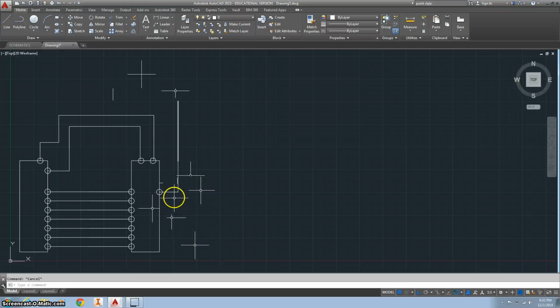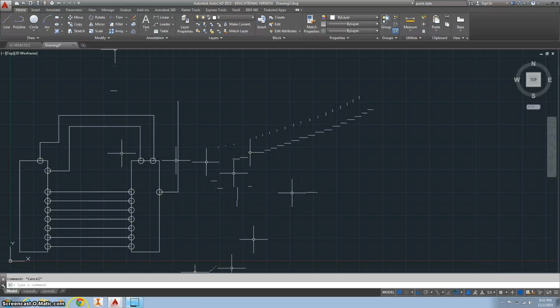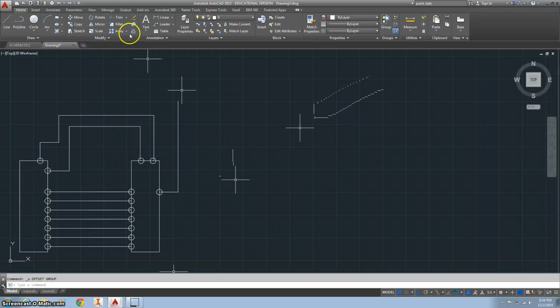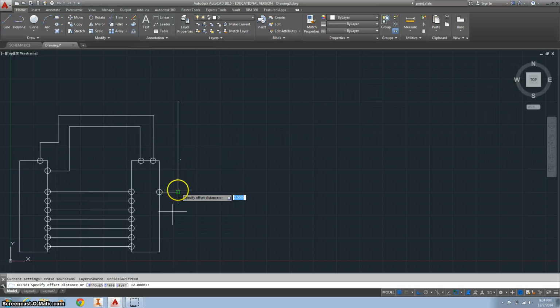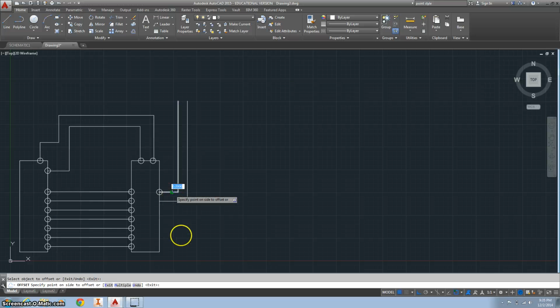and is it my graphic card, or why didn't it work? Look at all this stuff. Alright, so let's try this again. Offset, click on the line you want, specific. Alright, then it asks for a specific point. I'll just click this one. We want to select the entire polyline. We want to go down 1, so I type 1, enter, click it again, and there it is.